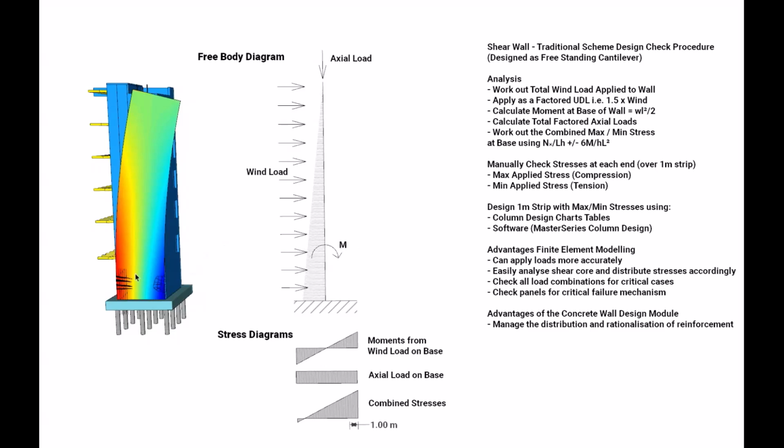We are checking a single wall panel here, but really the shear wall we're looking at is part of a shear core, and it will behave more like the hollow section I showed earlier. The correct procedure in this case would be to take the shear core as a whole, working out its section properties and determining its resistance from that. But for simplicity's sake, we will treat it as a single shear wall. So I won't be taking any values in here, to save a bit of time and possibly confusion.